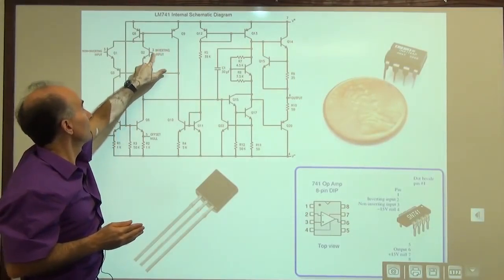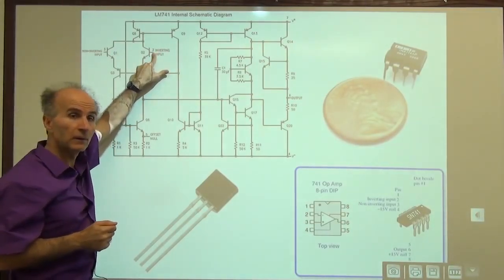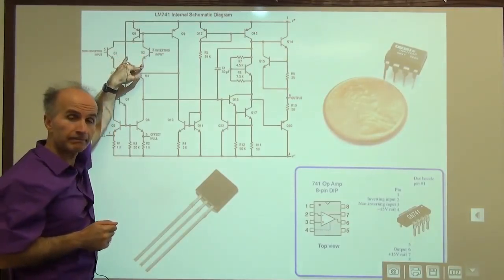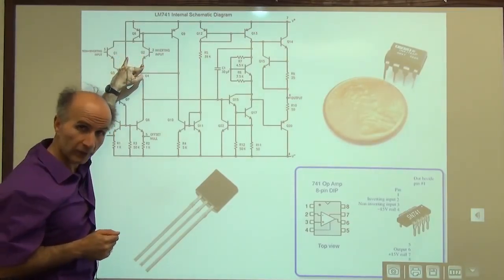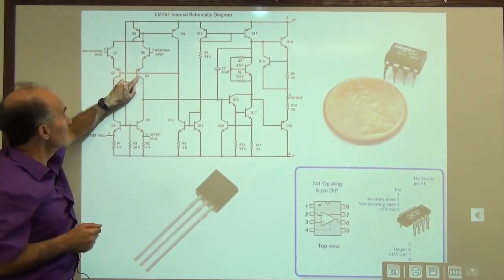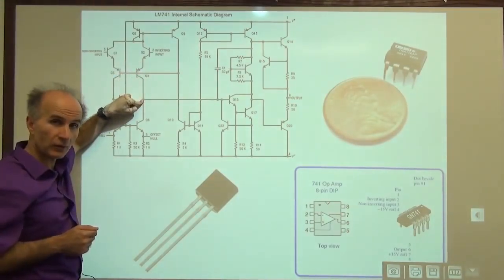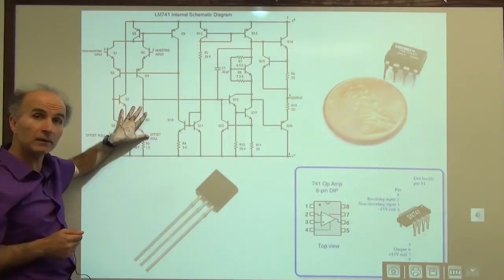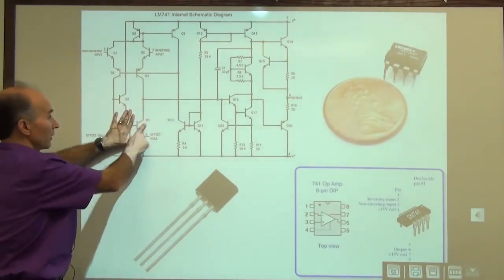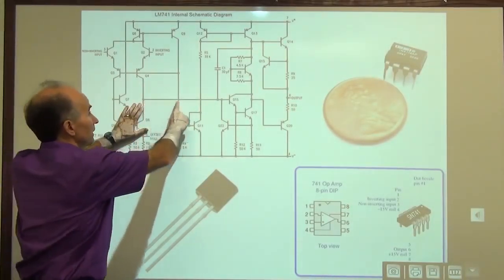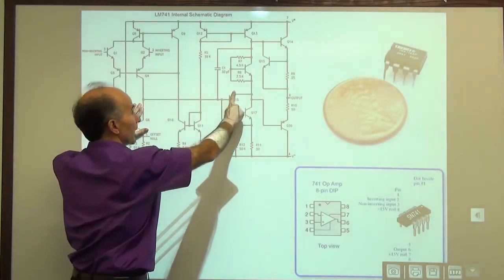The signal goes to the base of Q2 and evidently comes out of the emitter. So that's an emitter follower. Then it goes to the emitter of Q4 and comes out of the collector. So that's a common base stage. It has some sort of load, maybe a current source with degeneration, right? Then it comes out here and goes to another circuit.